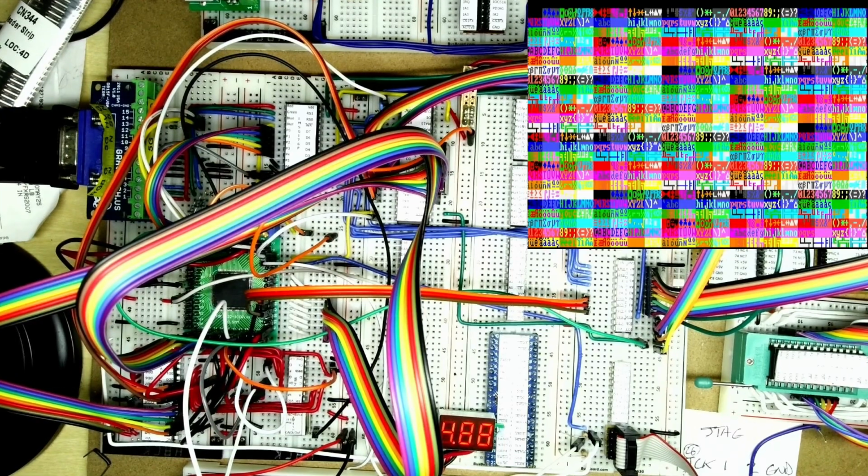So we've now got the attributes working, and we configured the PLD for the color register, control register, and status register. Now I need to do a bit more testing on that, and I need to update the test software to actually test all the attributes. So in the next video, we're going to do a bit more testing of the attributes and the blinking and things like that. And then we're also then going to add the video RAM and add the address latches and buffers to the video RAM, and then see if we can actually get some test patterns programmed on the display like we had in the previous series.